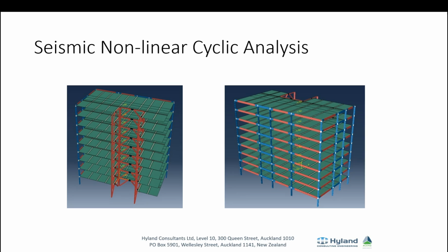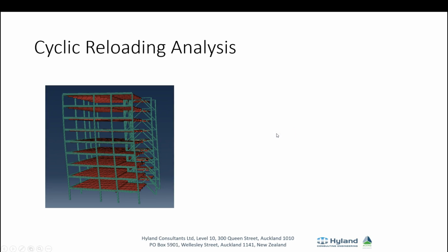These were ribbed to give an equivalence to composite steel beams being there. We were trying to avoid any potential for slab modes of vibration if we were to use dynamic analysis, and then we didn't. Particularly what I did here was a cyclic pushover analysis, so sort of reloading. So the question was, would these hinge zones at the links be able to sustain another earthquake?